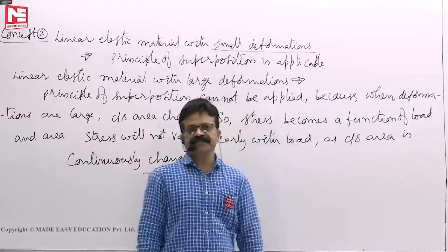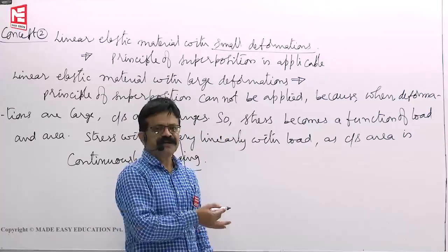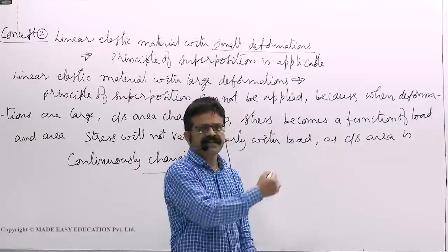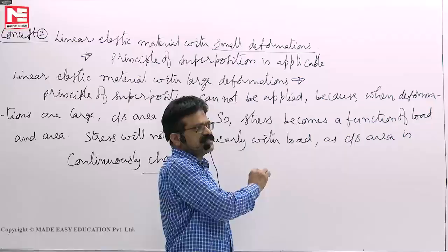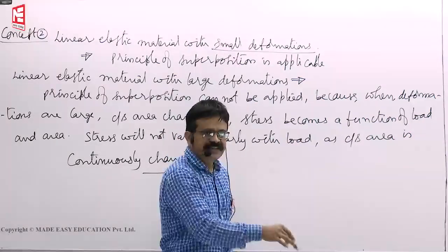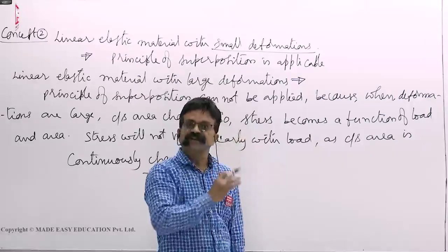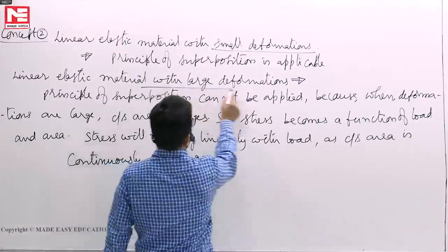This is what you have learnt. Small deformations are applicable, large deformations you cannot apply, because stress is directly proportional to the load only then. We cannot write that, because as the load increases, stress will not increase linearly, because area is also a variable quantity. So this you cannot apply.